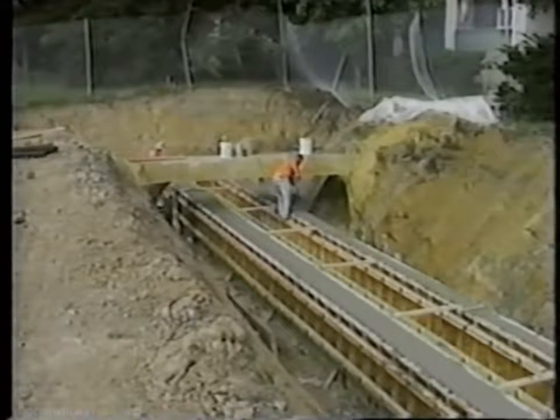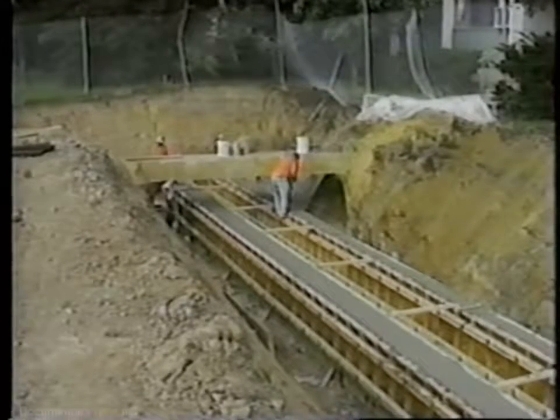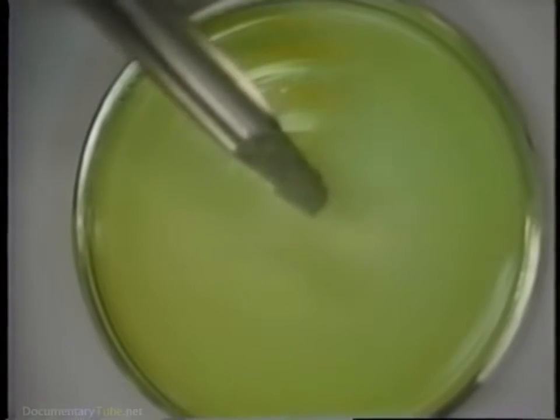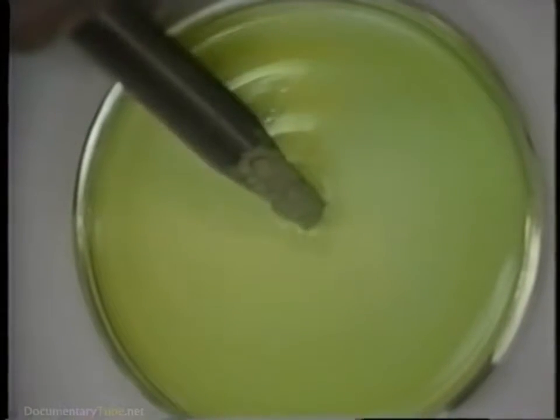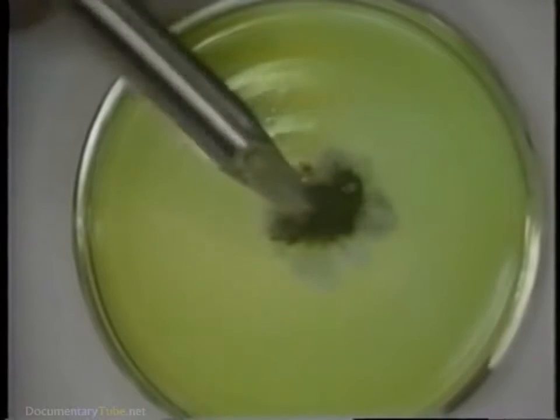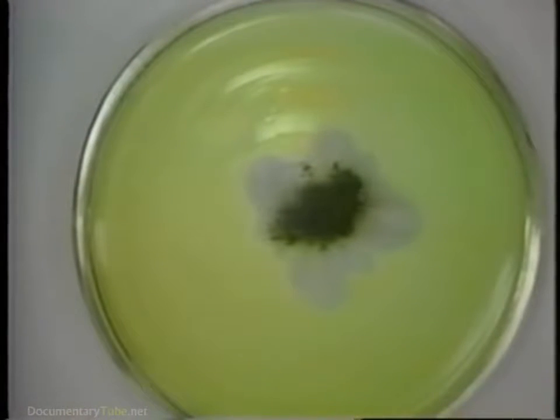will harden to create the necessary components of a concrete structure. The setting and hardening of concrete is caused by a chemical reaction between Portland cement and water. This can be demonstrated by adding a small amount of cement to water containing an indicator. The rapid development of a blue color reflects the release of hydroxyl ions from the dissolving cement.